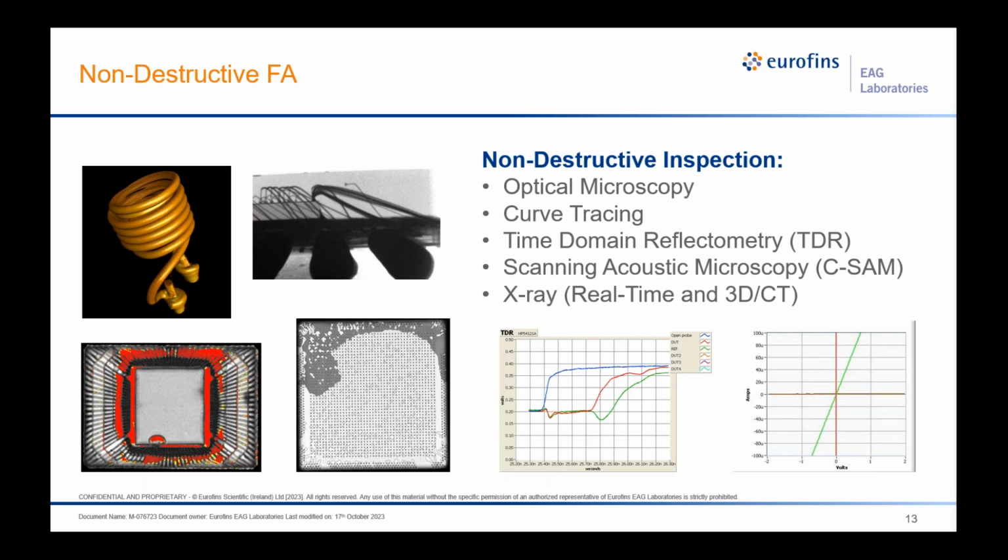The right image is simply an IV curve. It is essentially a pin-to-pin kind of curve trace. It gives us an idea of whether there's a short or an open, so it's kind of verifying. I think Winston talked a little bit about the IV characteristics and the benefits of doing it, even though it's not a fully powered test.